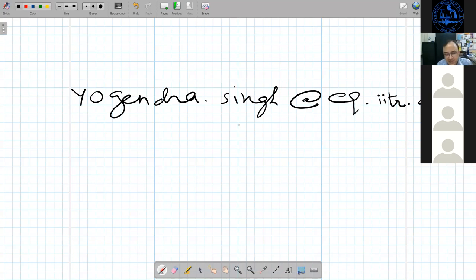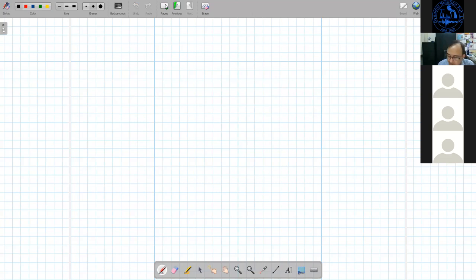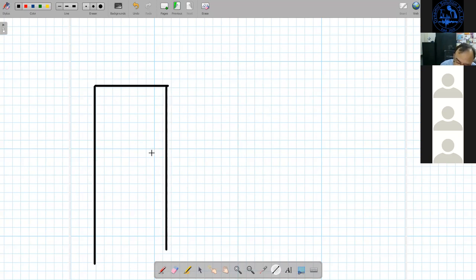If it is an RCC coupling beam, it cannot be replaced. But if it is a specially designed steel member, even with concrete coupling walls, we can provide a steel member here.